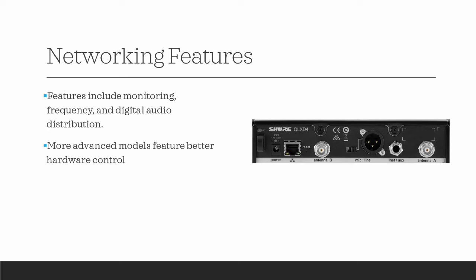As you broadcast a signal, you've got a peak on your spectrum analyzer, and the width of that peak determines how much bandwidth you're actually taking up. Even though we say that a wireless system may be set up at 509.575 megahertz, the reality is that signal is probably going from 508 to 510 or something along those lines.